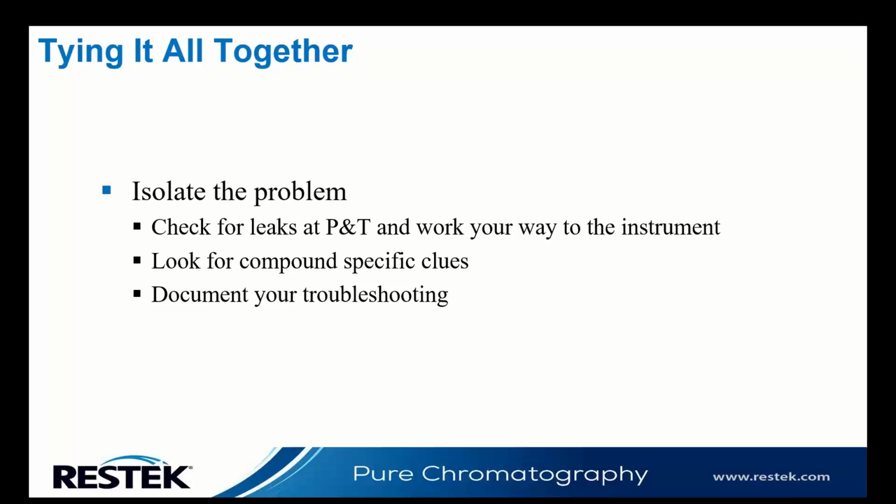So it's always good to bounce ideas off your colleagues. Or call tech service. So you can call Tekmar Tech Service or another tech service for help. And look at those compounds. Look at the response for all your compounds and look for clues from that. So you know which ones are active, you know which ones are cold spots, you know which compounds cause breakthrough. Those are all compounds that will give you clues to where the problem is.